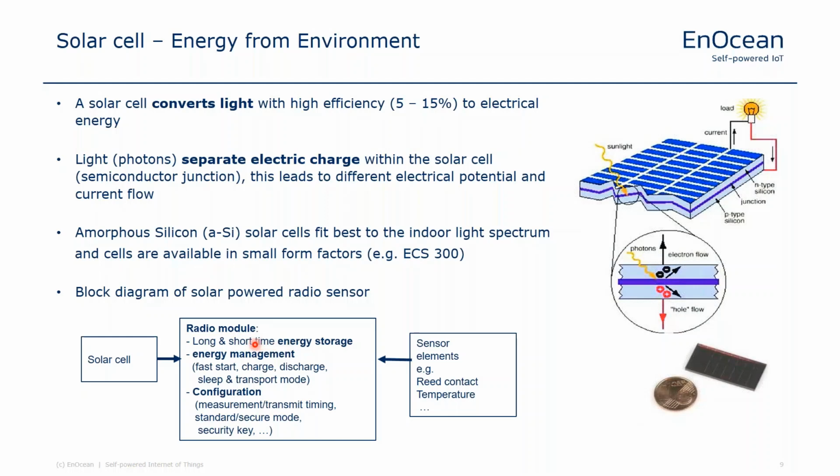The short time energy storage is very fast loaded and then good for operation. After this, the energy management switches to a long-term energy storage to save this energy for days. This is part of the energy management below, also the fast start feature. It also controls the discharge, so that we cannot go under a certain discharge voltage of the energy storage, and controls sleep and transport mode.